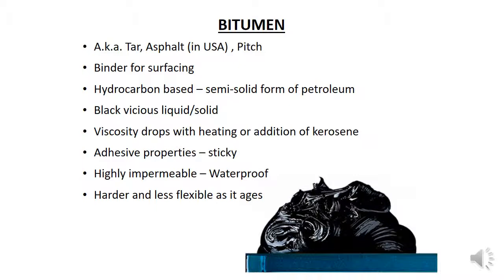Over time, bitumen hardens and becomes brittle. This can lead to cracking and loss of aggregate from the road surface. Therefore, bitumen surfacings need to be replaced every 10 to 15 years. This replacement often just involves laying a new surface over the existing and is called a reseal.